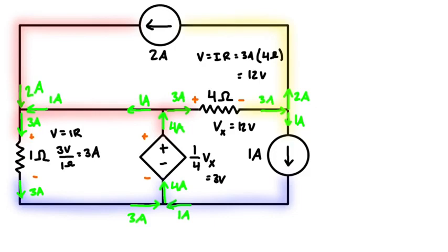Okay, if you want, it helps to draw a ground sometimes. You don't have to, but we can ground one of the nodes. There's only 3 options here, and you can do a little bit of trial and error, but it doesn't really matter which one you pick. I already know that this is going to be the best one, but basically if you pick another one, you're just going to get negative voltages. And you can just try by trial and error until you set your ground to be 0 and everything else will have a positive voltage.